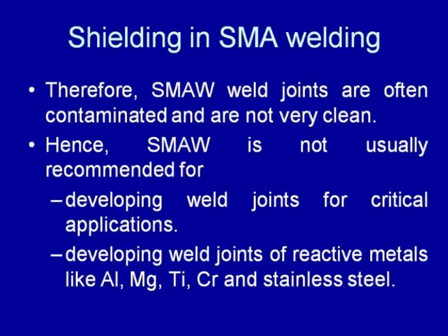Further, the improper cover formed by the thermal decomposition of these shielding gases leads to ineffective shielding, and because of this, the weld joint produced is normally found to be contaminated by oxides, nitrides and hydrides. The presence of these undesirable constituents in the weld metal decreases the cleanliness of the weld joint, and the decrease in cleanliness of the weld joint in turn decreases the mechanical performance.